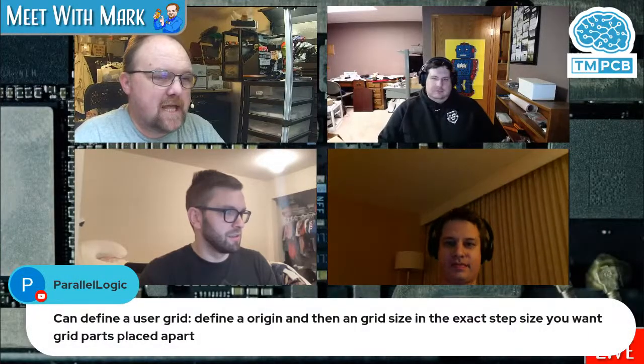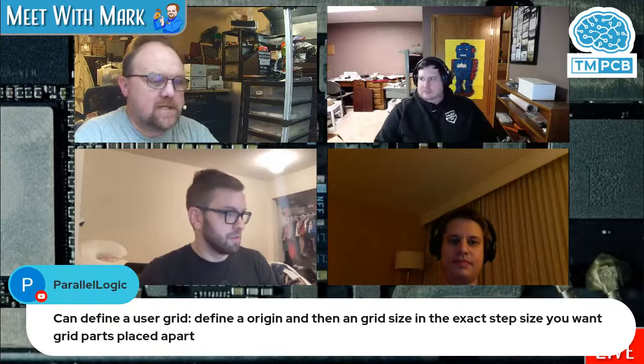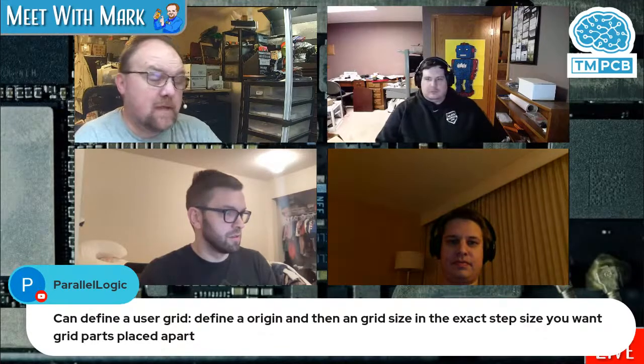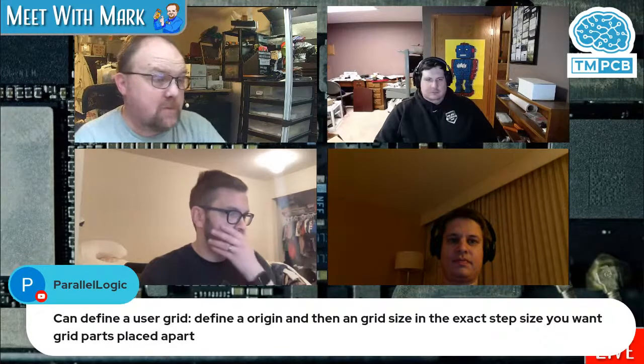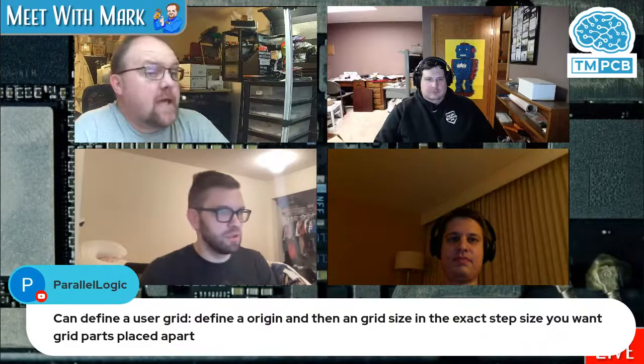So Parallel Logic shared 2 comments. One, you can set a custom grid, X and Y size, so if you want to lay things out on a 19.05 millimeter grid, theoretically you can. You just set that. And then he said it's also useful for putting test points at 100 mil centers throughout your design to line up with the protoboard test rig. Well, thank you so much, Parallel Logic.